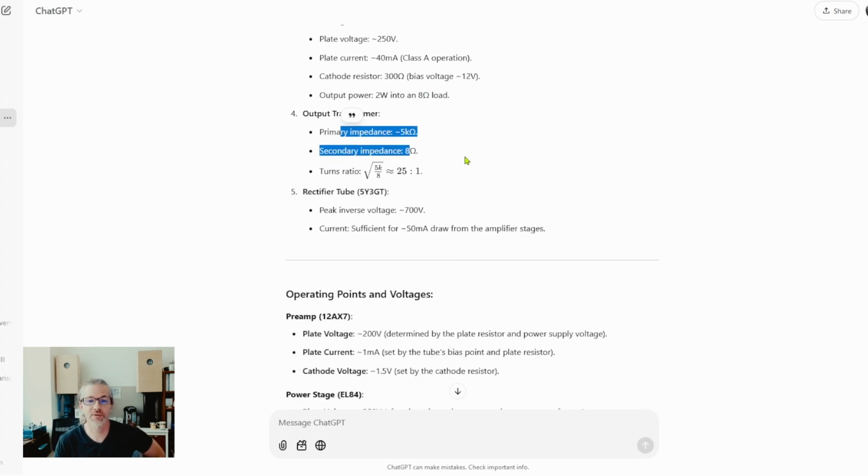My recommendation for a single-ended amplifier using EL84 as an output tube is to get an output transformer that has an ultralinear tap and put in a switch, so you can switch between ultralinear mode and triode mode. And when you're in triode mode, put a 100 ohm resistor in there, so there's a 100 ohm resistance between your plate, the anode, and the grid.